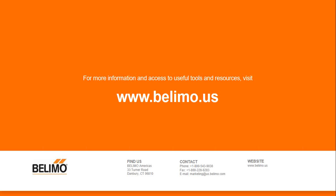Next question is, can the energy valve be used in applications where the flows are over 713 GPM? That's a really good question. Yes, it can. We can parallel energy valves, 2 or 3 energy valves. If you look on the cover of our current PGPL, you will see a parallel application with 3 energy valves installed. So yes, we can certainly do that to accommodate higher GPMs.